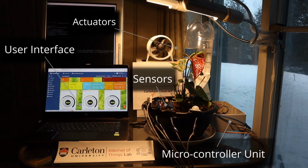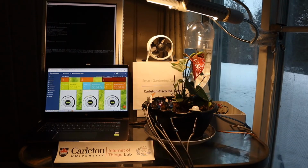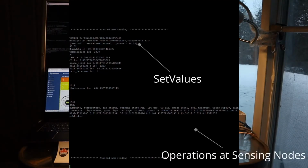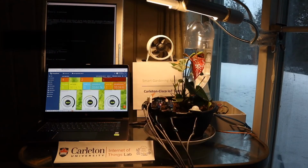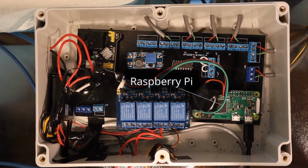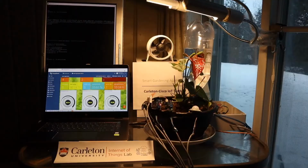As observed here, a user can monitor and control different environmental parameters such as temperature, moisture, and light with the help of the IoT testbed. First, set values for each parameter are assigned using ThingsBoard, then the comparison of these values to the sensed values is derived by the Raspberry Pi. Set values are received by sensing nodes from the MQTT Cloud, which is hosted by the IoT Lab at Carleton University.